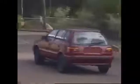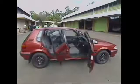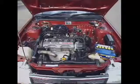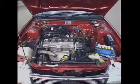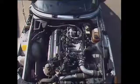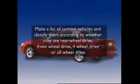Front-wheel drive vehicles use the front wheels to pull the vehicle along. In light passenger vehicles, it gives lighter body weight and increased interior room. The engine and transaxle are at the front and can be mounted laterally, that is, the engine is parallel to the front axle, or longitudinally, where the engine is in line with the center line of the vehicle. Make a list of current vehicles and classify them according to whether they are rear-wheel drive, front-wheel drive, four-wheel drive, or all-wheel drive.